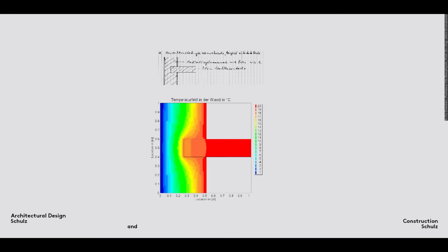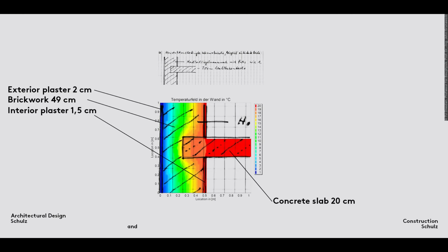A structural thermal bridge exists when weak points are created in the building shell due to the type of joints used. Here you can see what happens when a reinforced concrete slab is laid on a vertically perforated block wall. The reinforced concrete has a higher bulk density and thus greater heat conductivity than the blocks, and the thickness of the block wall is halved at the point where the slab is supported in it. As a result, heat transmittance at this point is significantly greater.